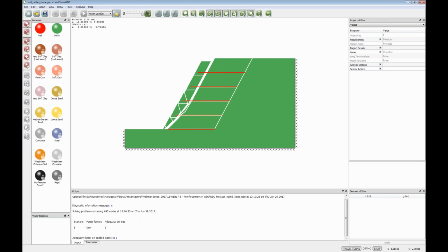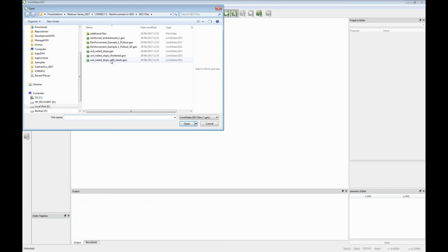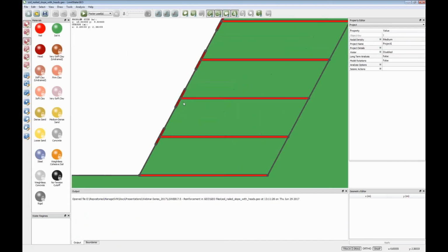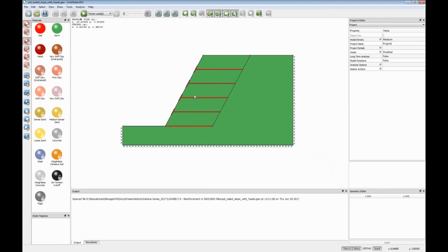Okay. I've got a question about, is it possible to apply forces between geogrids and facing elements? I've actually got a model. This one's for soil nails, but you can actually model, here I've got something that's partially facing. So effectively what I've modeled here using the same engineered element is either facing or a nail head here. In fact, for simplicity, I've modeled this as essentially a two-dimensional strip going into the diagram, which these nails are connected to, and they will clearly provide more reinforcement to the soil.